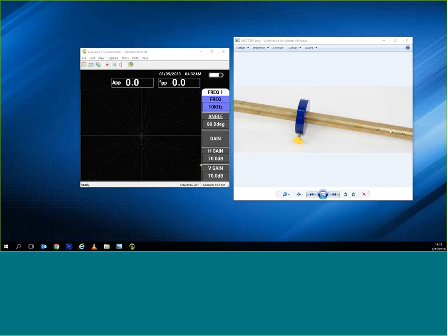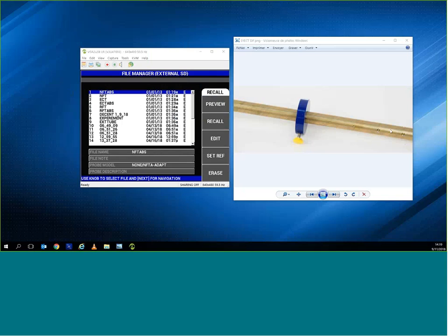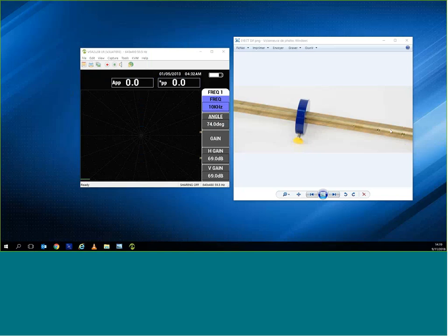Okay. So to simplify, I've created pre-saved files. So we're just going to load the first one, which is eddy current differential. Now we're going to load that. Now this file already has the auto mix function enabled. So what we're going to scan, first we're going to null, we're going to bring all the points back. Now what we have here is frequency 1 is right here. Frequency 2 is in a strip chart kind of look. And we have the mix channel.